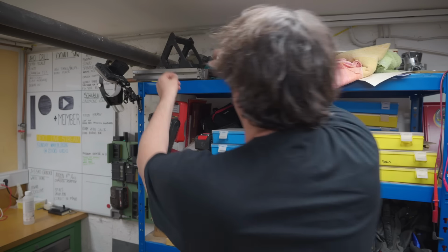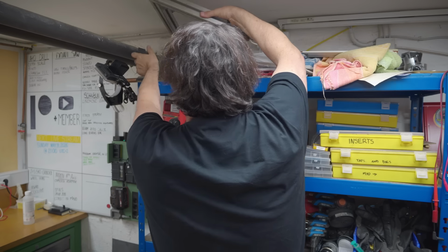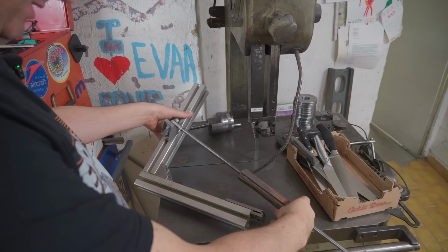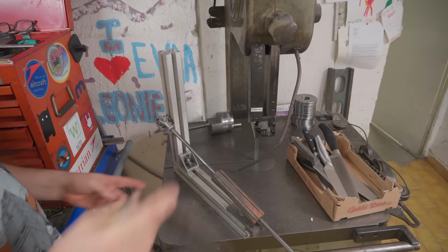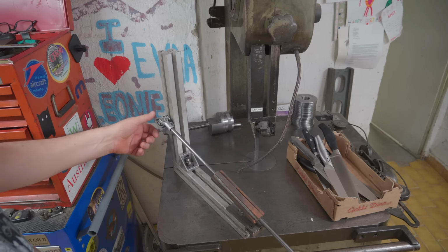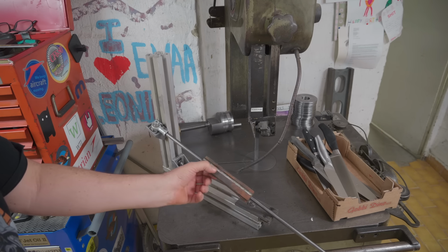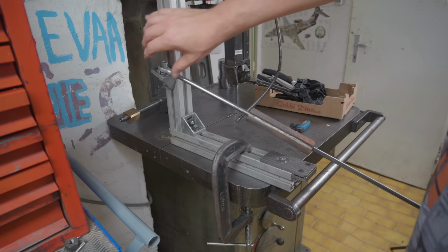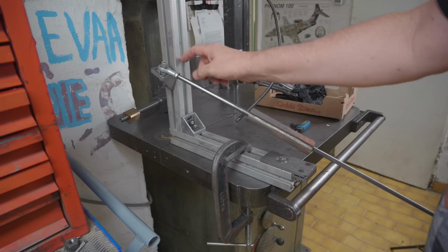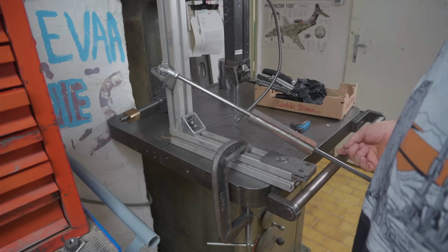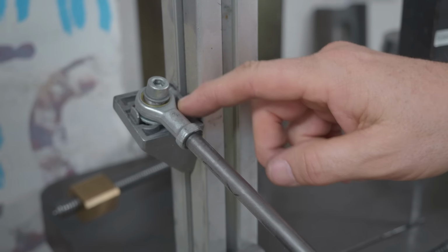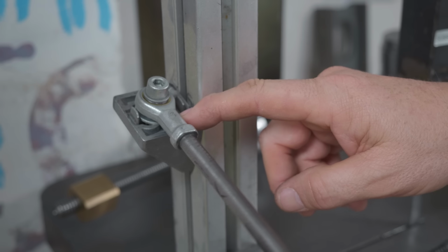Not sure if I've ever shown this before. This here is my knife sharpening jig. I know you can buy these things for hundreds and hundreds of euros, but I just whipped this up out of a couple of aluminium profiles. Piece of linear bearing. Had to cut the alignment bits off this bracket so that I could rotate it. The height of this adjusts the angle. I think it's at 20 degrees if I remember rightly. The linear rod goes into a spherical bearing to give a bit of motion.